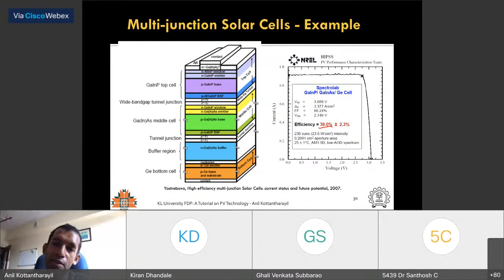On the other hand, we have seen this silicon solar cell, right, where we had silicon and silicon oxide on both sides, silicon nitride on the top and aluminum oxide on the bottom. So we had basically 4 materials, but here 17 materials. Okay, and when you're depositing this by many different techniques, the possibility of getting defects is fairly large. As a consequence, you cannot make a very large area of this, and the cost is going to be enormous. So that is actually one of the major issues, though you can ideally get 39% efficiency.